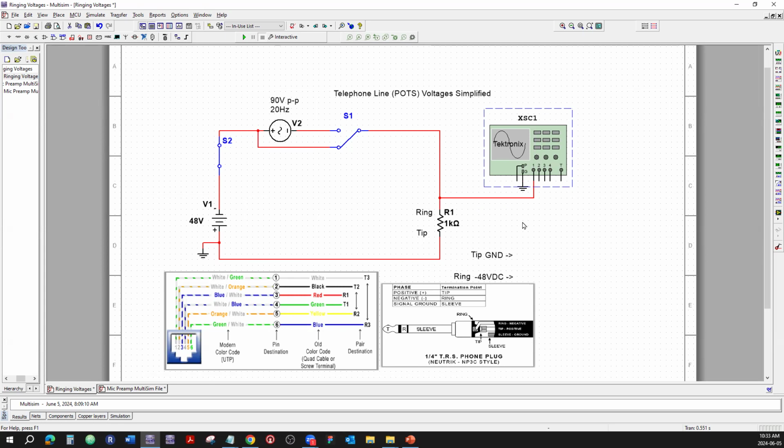So here's a terminology that you might hear. There's no dial tone. Okay, there's no dial tone. Should there be? Yes, they should be, they have purchased the telephone line here, but there's no dial tone. And you might hear a question, is battery present? Well, what they mean is, is there 48 volts present across that? So the telephone line, as it idles, has 48 volts across.